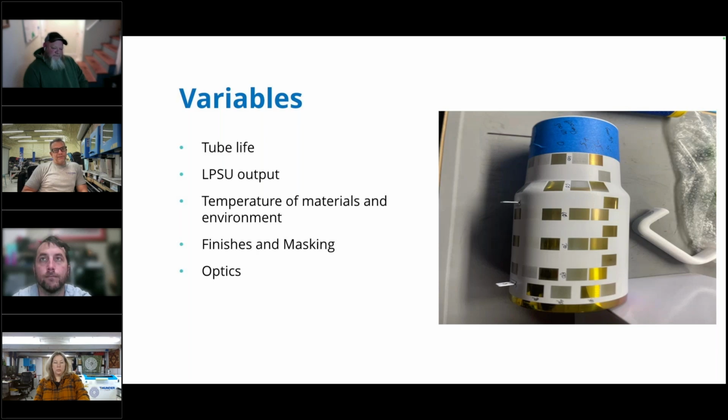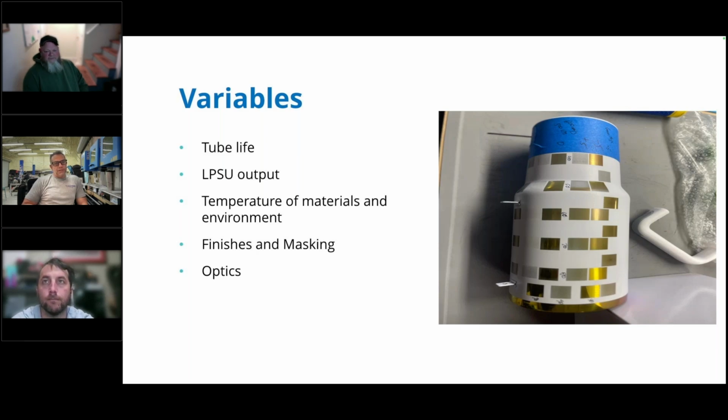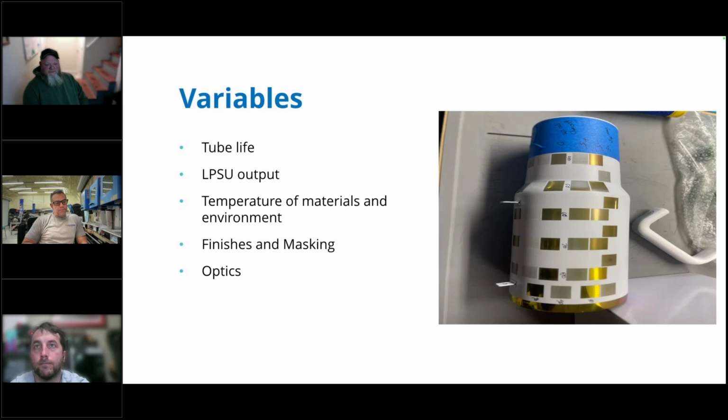Just masking, if you're doing an engraving, can change your entire world if you don't butt them up together. If you start overlapping, you're going to have peaks and valleys everywhere that is overlapped. Ask me how I know. It's horrible, and there's no way to fix it because now you have different levels of the material. But just that small little bit makes a huge difference. It's a different type of material, there's a glue there. So all of those finishes and maskings can change settings greatly.